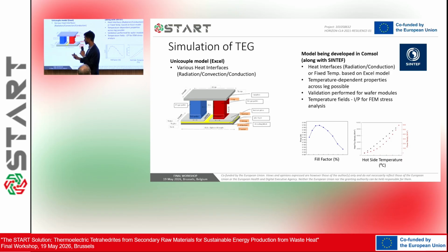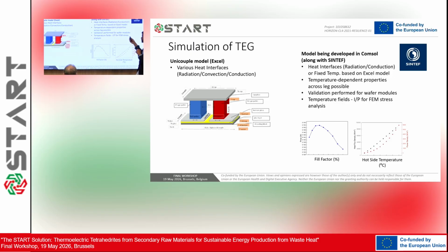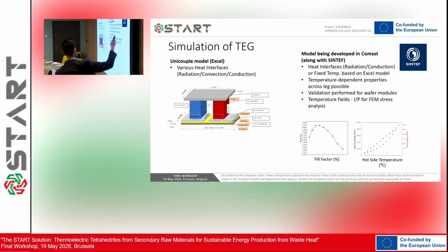And here we wanted to see what the sizing of the pellets needs to be to couple to the combined heat and power application. So the heat flux density was defined, and then we did the sizing of the pellets themselves. That was first done analytically, and then we transferred that into a COMSOL model that we built, and also along with SINTEF optimized the fill factor for such a unicouple, where it peaks at a certain value, so that's per unicouple.